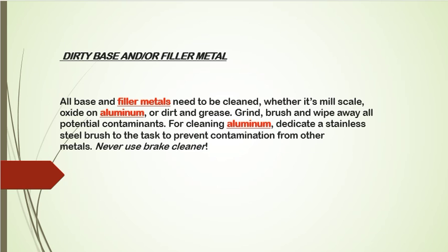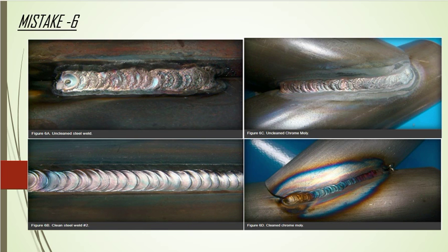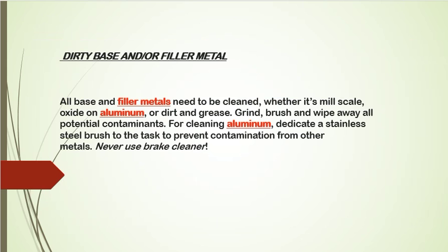So this is dirty base metal and filler metal. Why is it created like this? This is the dirty steel weld, and the base metal and the filler metal were not clean. It was mill scale. That's why it is happening like this.